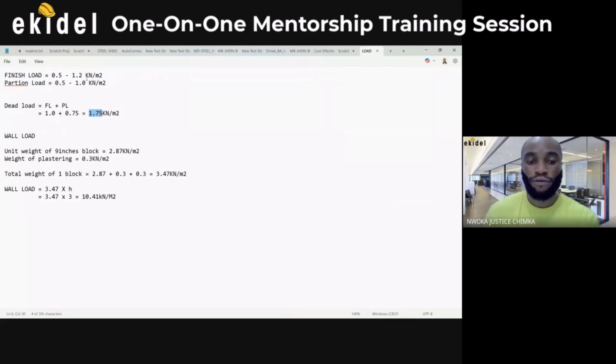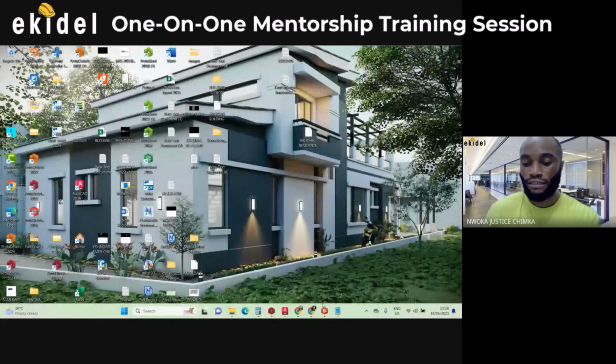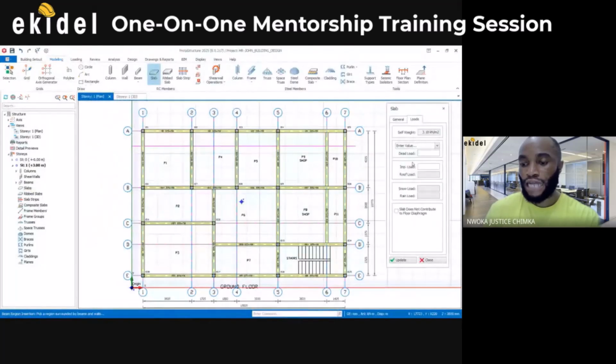So with that, let me assume that this building here does not have much load. So I can say 1.2 here and then 0.5. That gives me 1.7. So 1.7 as my dead load. So I'll come now, minimize this, and then add here that says dead load 1.7.